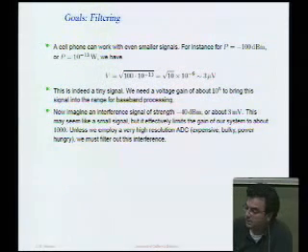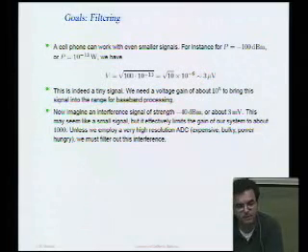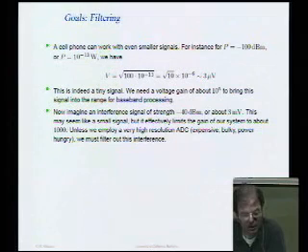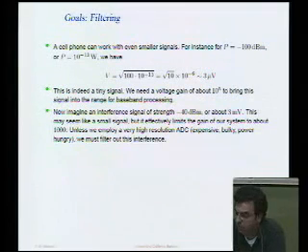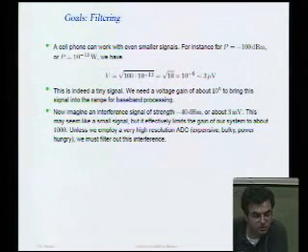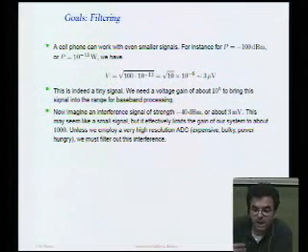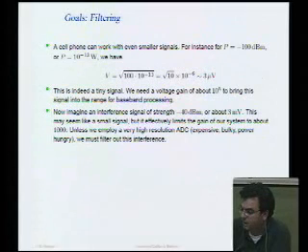And to gain some intuition about how small that is, go in the lab and look at an oscilloscope. Start out with, let's say, 100 millivolts, and then keep making the voltage smaller and smaller. And as you get into the microvolt range, you'll see that it's all blurred out, it's all noisy. That's because of the finite dynamic range of that oscilloscope, and also because of the noise that's present with that signal. That noise, as we'll learn about in this class, is proportional to the bandwidth of your observation. And the more data you push through a link, the more bandwidth you need, and therefore the more noise that will enter your system.